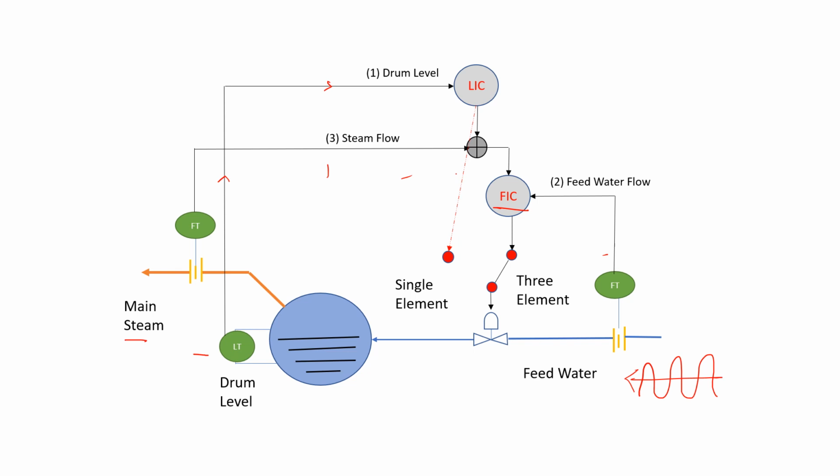No, because when the boiler starts up, the flow of the main steam and the feed water flow are both insignificant, and the flow meters of the feed water flow and the main steam flow often do not provide an accurate reading at the condition of startup. So at startup, instead of three element, single element control is used.